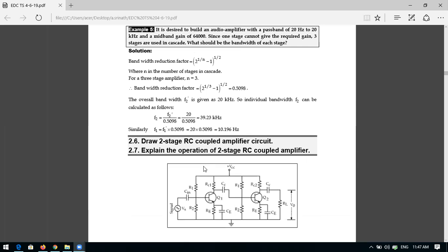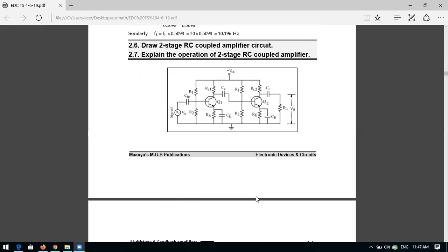If you see the circuit at high frequencies, what will happen? It behaves like a simple wire, directly connected to the second stage. That means the second stage is connected as a load to the first stage. So the load increases, which means the current drawing capacity is reduced more and more. That is the reason the voltage gain also falls.